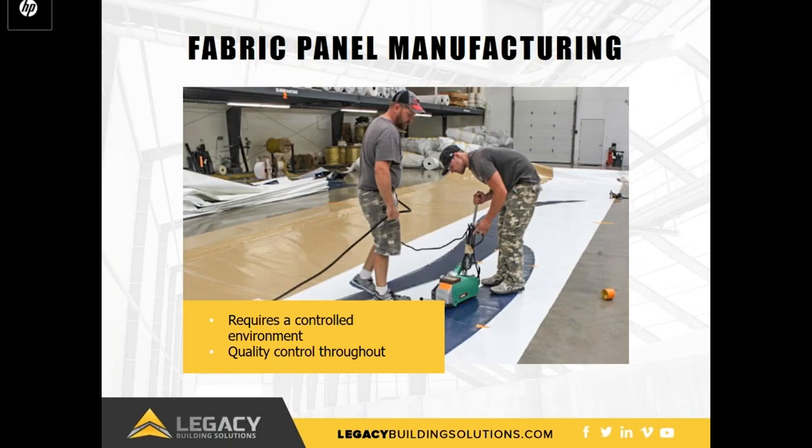Panels must be tested to tight tolerances that account for the precise amount of stretch present in any given fabric. Precision manufacturing is especially important to incorporate the required amounts of pretension when using individual fabric panels, as the size of the fabric is what provides the biaxial tension on the panel and prevents excessive movement and premature wear.